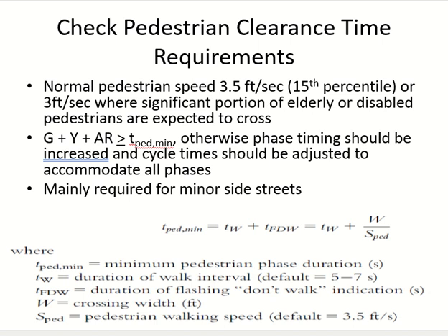Where can we use it? We can use it here. If you believe this value is not suitable for you, you can calculate the same thing for TW as well: W upon speed of pedestrian. But which is the speed of the pedestrian? Normal, not this one. This is higher. This is the end, when the signal is flashing. The pedestrian already has a warning that the signal is about to close, so he will go faster. Right now we are taking the recommended value, which is in this range, 5 to 7 seconds.